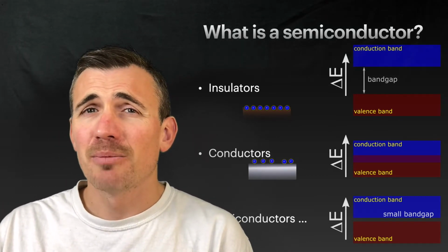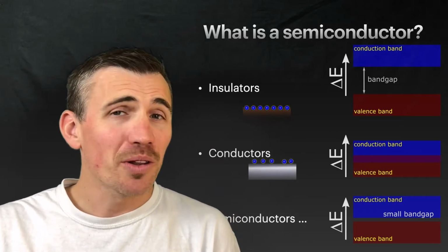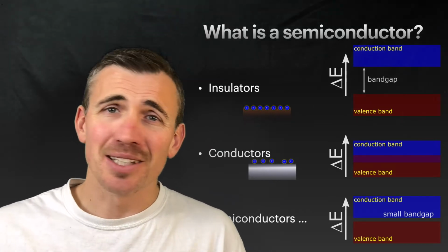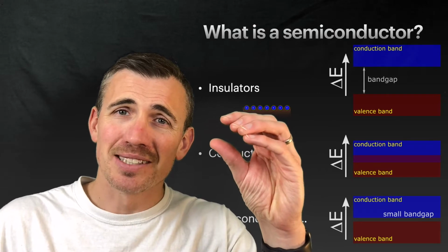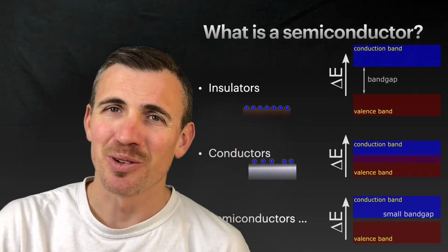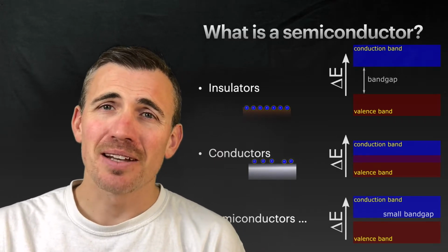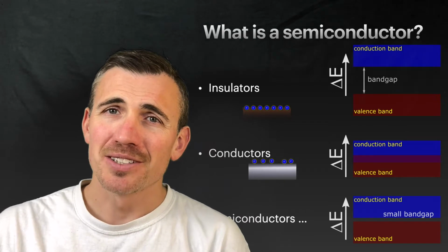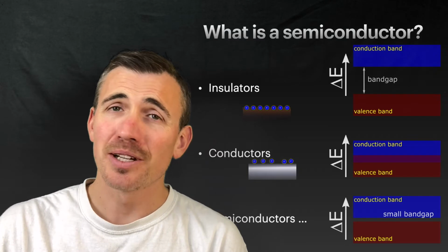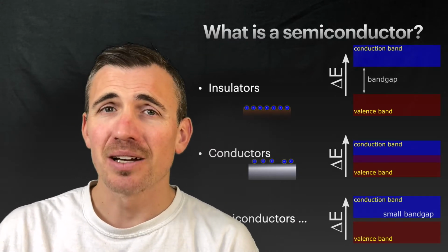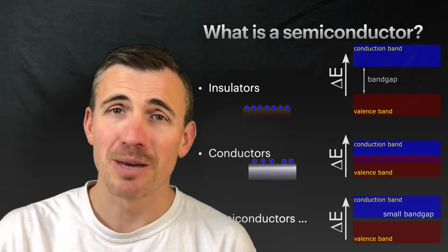And we're going to attack it by looking at three levels or three properties of semiconductors that make them useful. Note that it is not the case that an insulator has such and such a resistance, a conductor has a much lower resistance, and a semiconductor is in between. That would not be useful, would not be worth talking about. It's actually that we can apply external factors to these semiconductors and change whether or not they behave like a conductor or an insulator. And it's this engineering of its electronic properties that really make semiconductors almost magical devices.